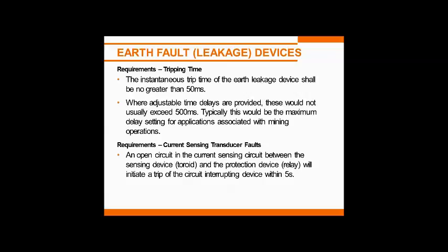And also provided in the standard is that the maximum delay is 500 milliseconds. Now, it's quite different to some of the earlier relays we've sent out with 2.5 seconds or 5 seconds delay. Now the new standard requires a fairly strict 500 milliseconds. So on the relay, you just simply can't set any more than 500 milliseconds.